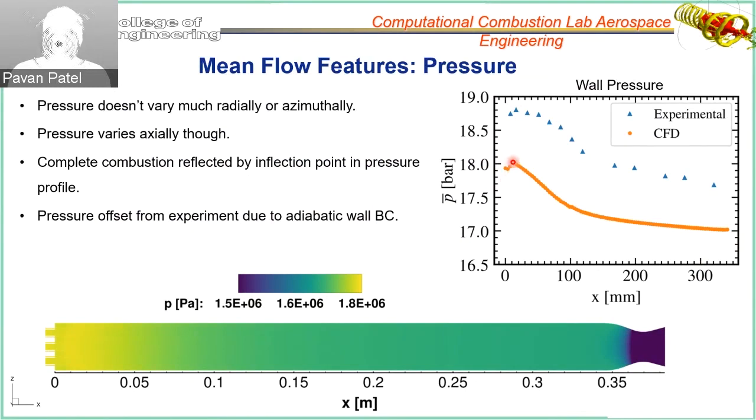And then because of combustion, we have this steep pressure drop. The heat release due to combustion accelerates the flow, and that acceleration increases the velocity. And because the velocity goes up, the pressure goes down. How quickly it combusts is how quickly heat is released. So if you have very quick mixing and very quick combustion, this is going to get steeper and steeper.